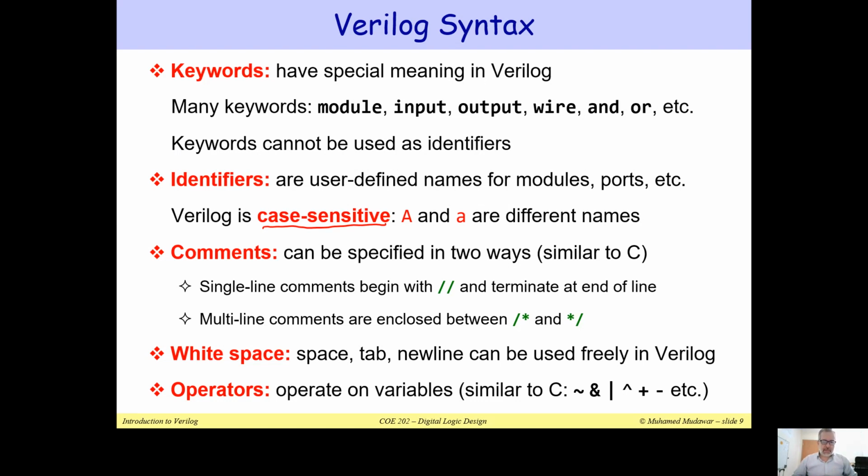You can also write comments. There are two types of comments that you can use in Verilog. You have the single line comment, which starts with // and terminates at the end of the line. And we have the multi-line comment, which is surrounded by /* and */ as in the C programming language.